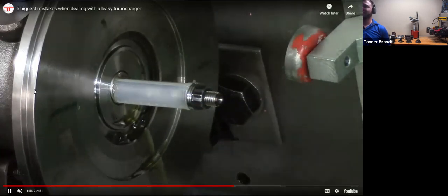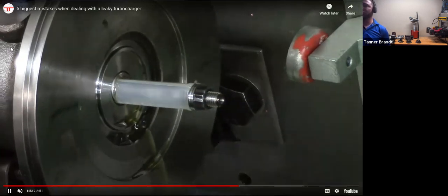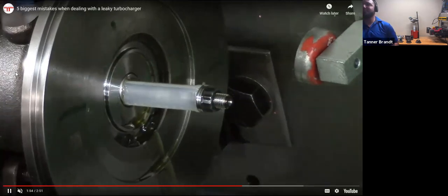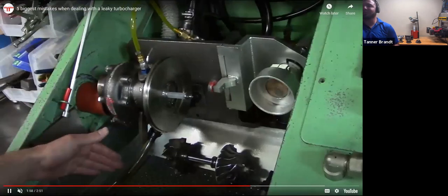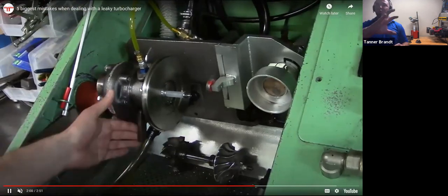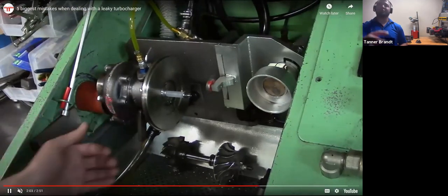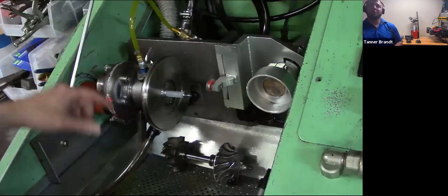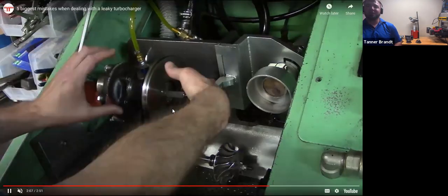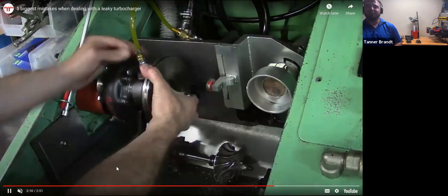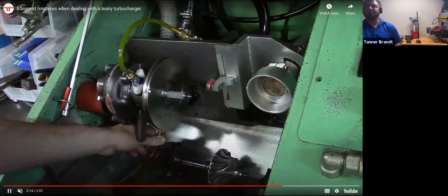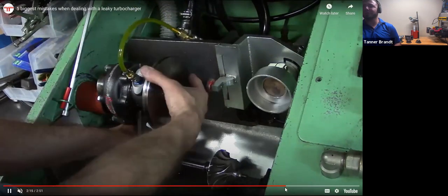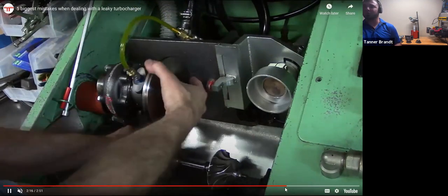Well, the bearing housing on a turbo can move. So let's say this bearing housing that he's got over here, right here in the center section, was twisted and was in the wrong spot. So your drain tube now was twisted. When that happens, the oil is not going to flow out of there correctly, and it's going to pull up and come out of that. And I'll show you in a second why that happens when we look at a cutaway of a bearing housing.